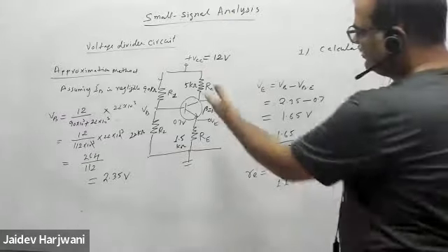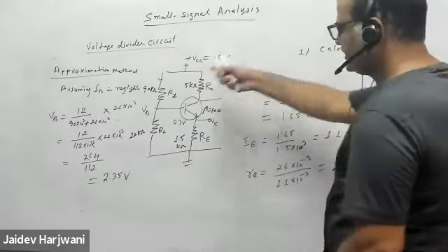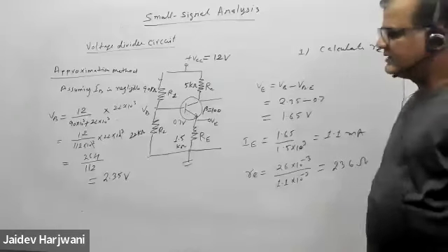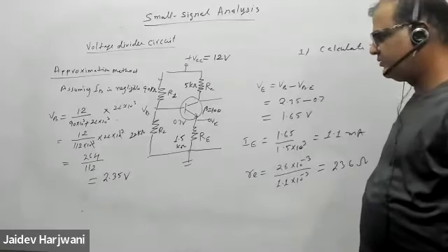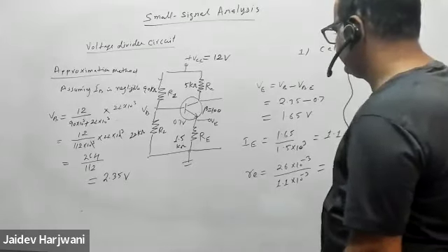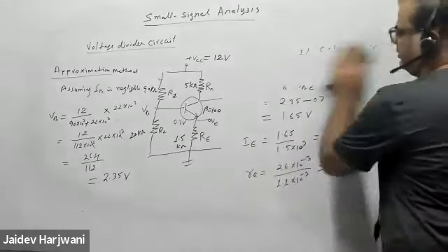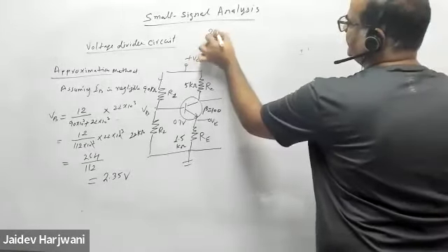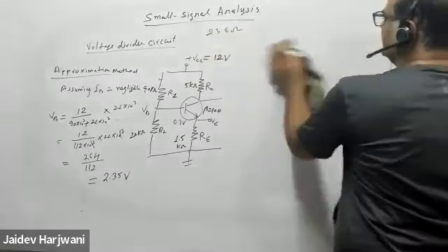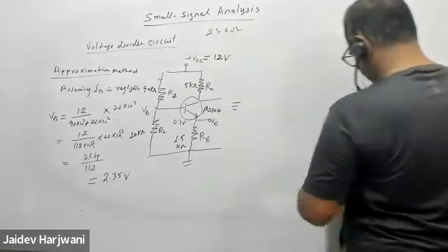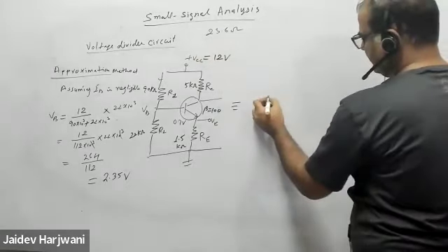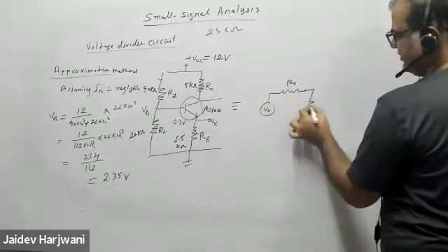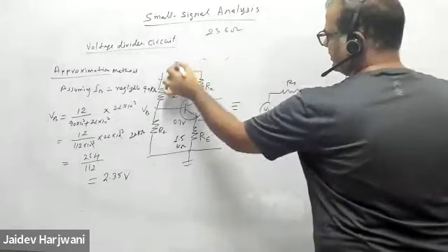Okay. Now replace this circuit by the AC equivalent. Even if you don't need to replace, because now you remember the formula, just one time I'm replacing this one. So remember this value 23.6 ohm. Now the equivalent circuit will be what? For AC, you will have this VS, RS, and you have to make this short circuit.